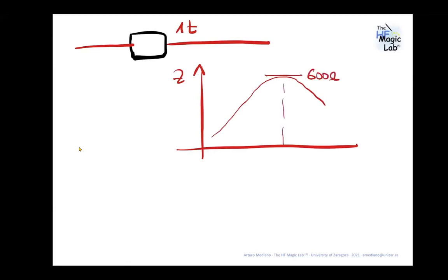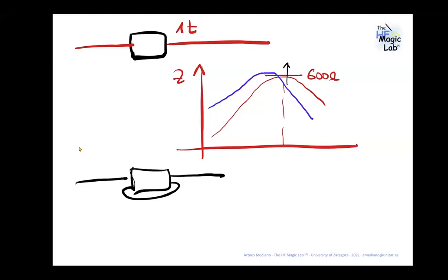If you take the cable and make a second turn through the ferrite, the idea is that it's like introducing 2 times the impedance. So you would expect the impedance you are offering to be higher. But the effect in a real ferrite is that usually you increase the impedance, not to double the value, and the peak is decreased.